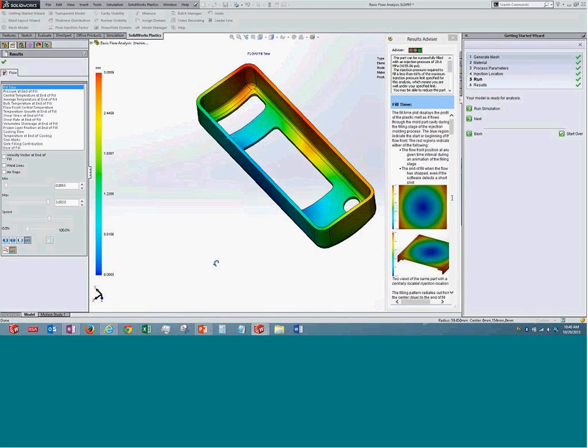In plastic parts or plastic designs, typically they are all of uniform thickness and can be represented with shell elements. So nothing wrong. But in cases where it is not possible to represent those parts with thin structures like shells, I have to use solid elements. So there we need to move to solid elements.